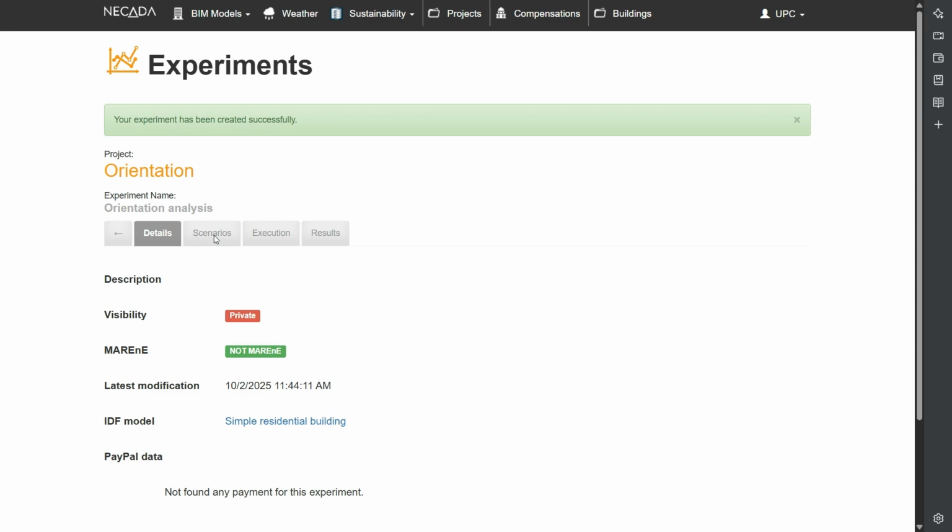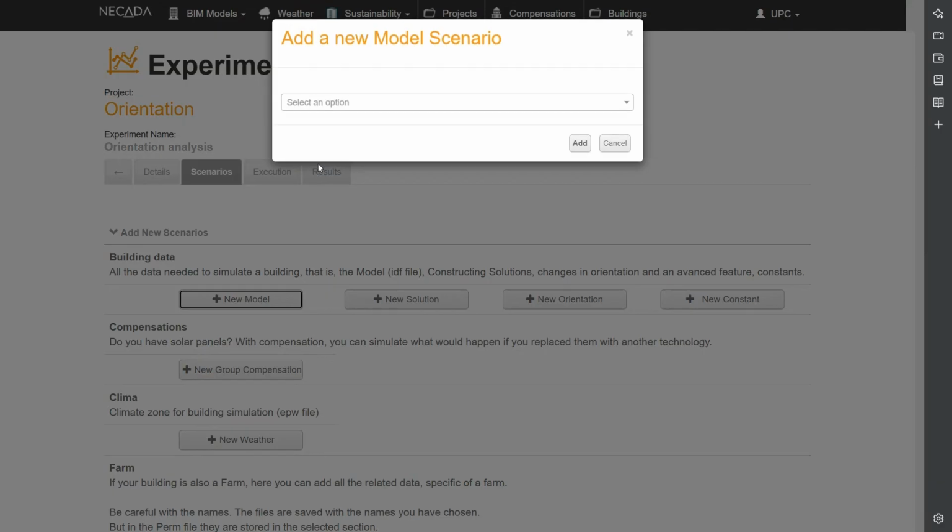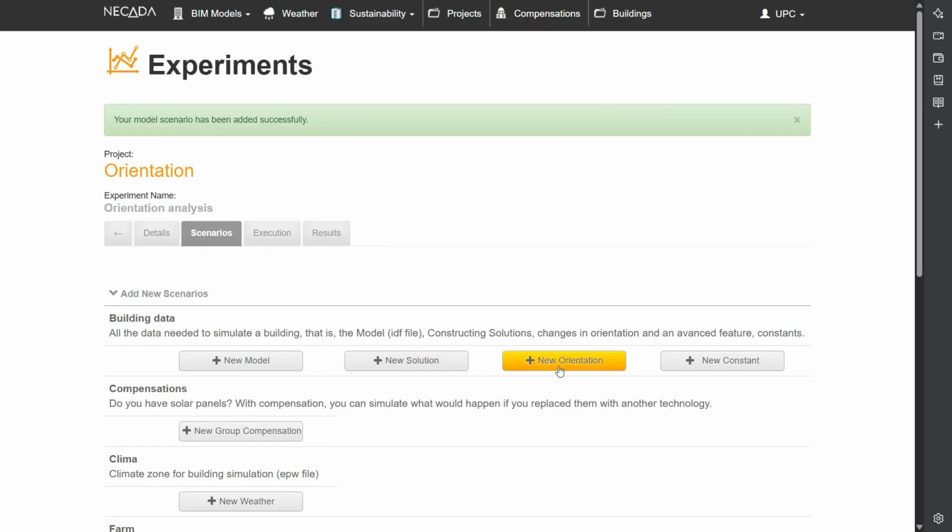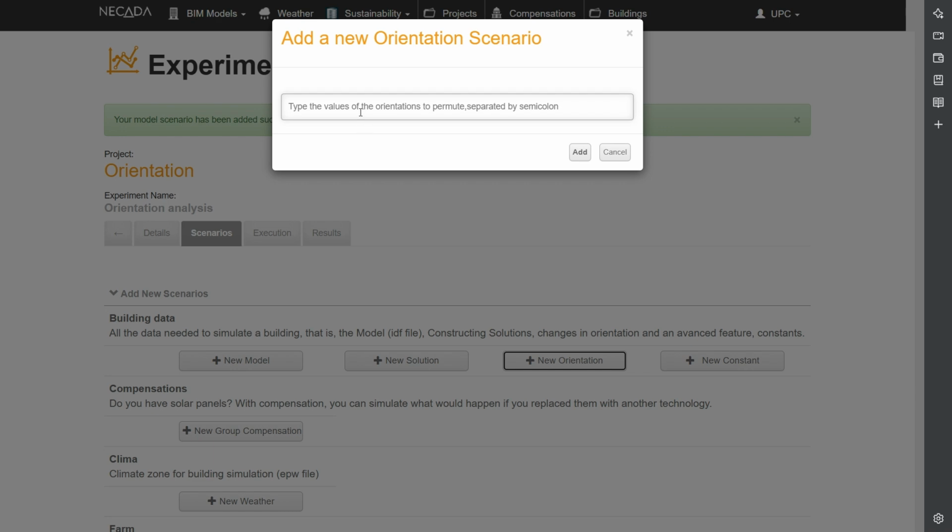By examining these variables, we can gain insights into how orientation affects the building's overall efficiency and sustainability. Once the parameterization is complete, incorporating the orientation, building, and weather information we wish to analyze, we can execute the model. The duration of this execution depends on the number of final scenarios generated from the combination of value factors. In this straightforward example, we will analyze only 4 scenarios.